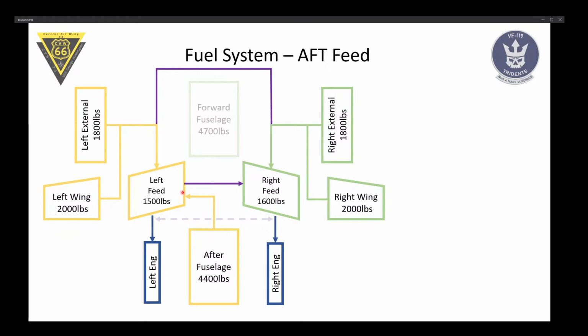Basically this is how this motive flow stuff works. And you only need one pump per side for all of this transfer to work, and this is the engine-driven pump. So you have the engine-driven pump, this is the motive flow pump. You have one motive flow pump, which basically provides the fuel transfer between all these tanks. And there's no control for that because it's always on.